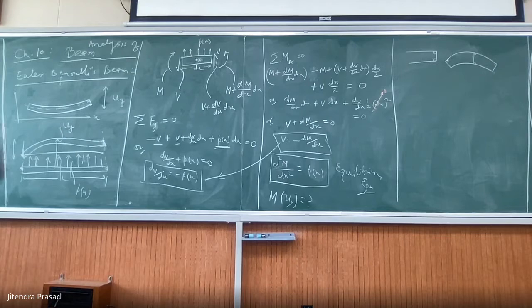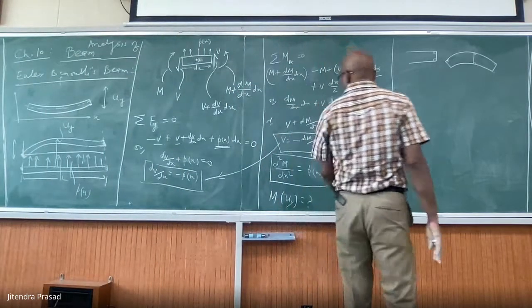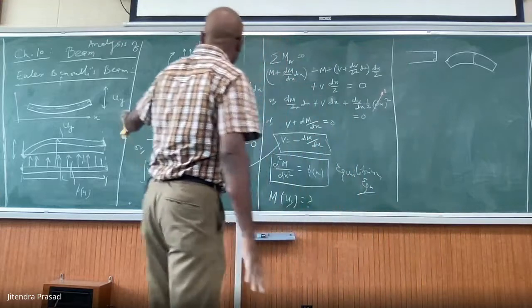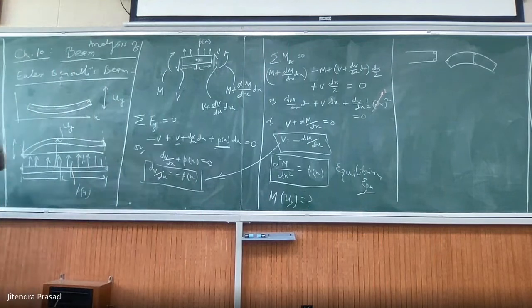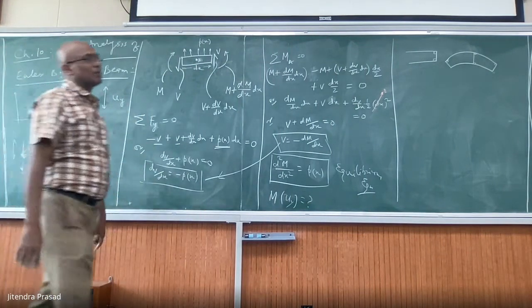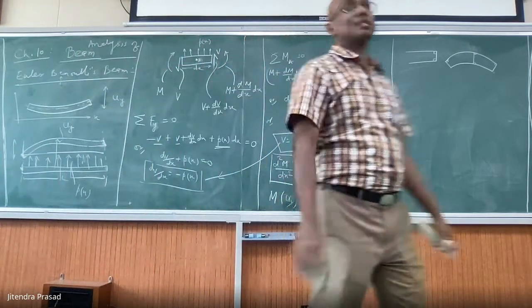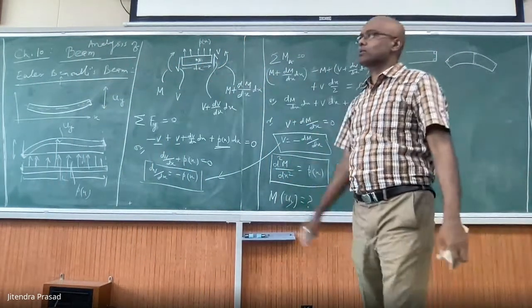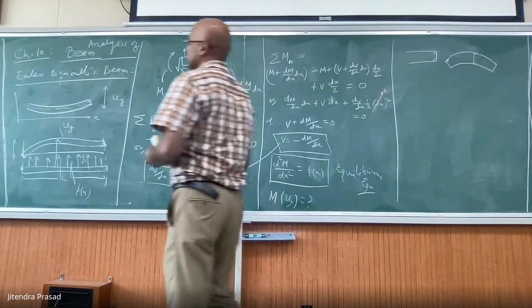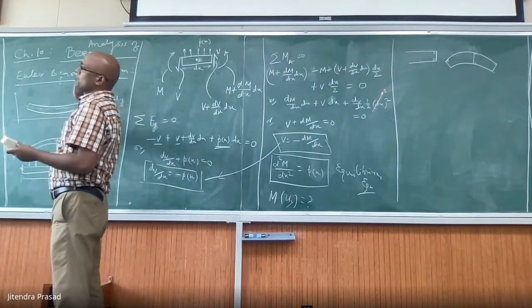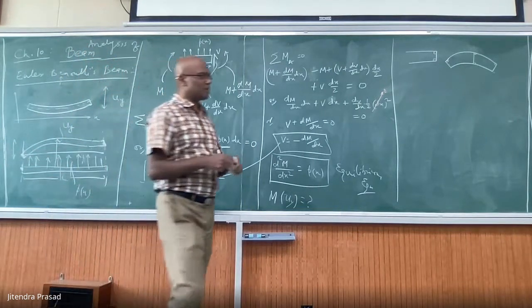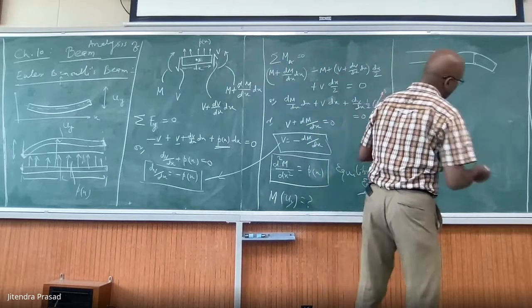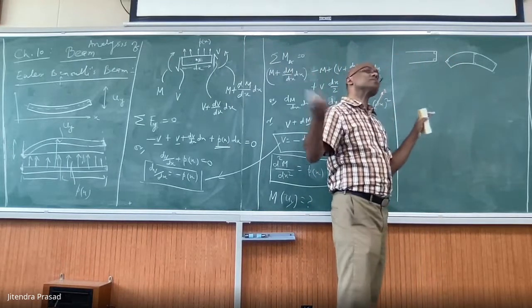So that's the thing. And this whole derivation is based on that, and hence Bernoulli. Later on, you will find out that this does not work for non-linear cases, for high displacement cases. So for small displacement you can do it. If you have a larger displacement, then this will not work. This will give you a wrong answer. Or what you can do is make small elements and solve.